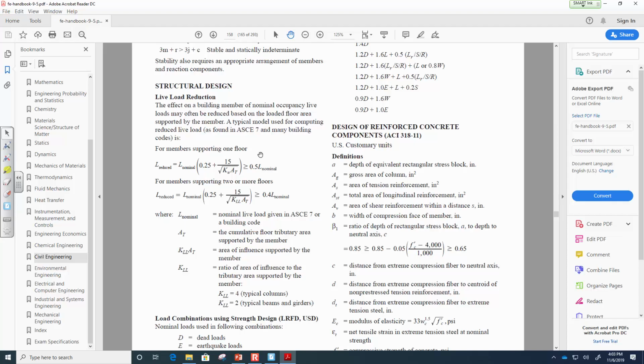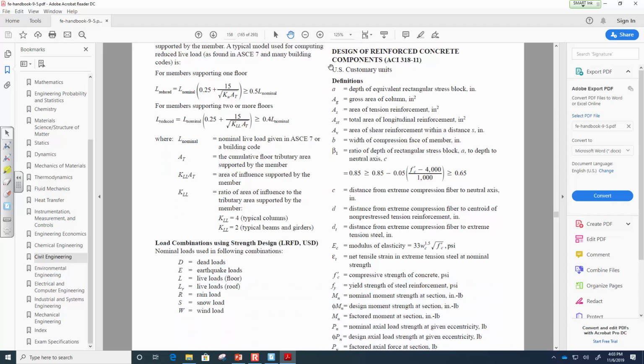When you look at concrete design, for those of you who had that course, what you'll see first is the notation. If you remember in concrete design, we were pretty hyper aware of what symbols we were using for what dimensions. Like, when I used the dimension d, I didn't just throw that around flippantly. d always meant something. It was from the top of the beam to the center of the tensile reinforcement. d prime was the top of the beam to the center of the compressive reinforcement. Remember that? Then we had bw, hf, and all of that stuff.